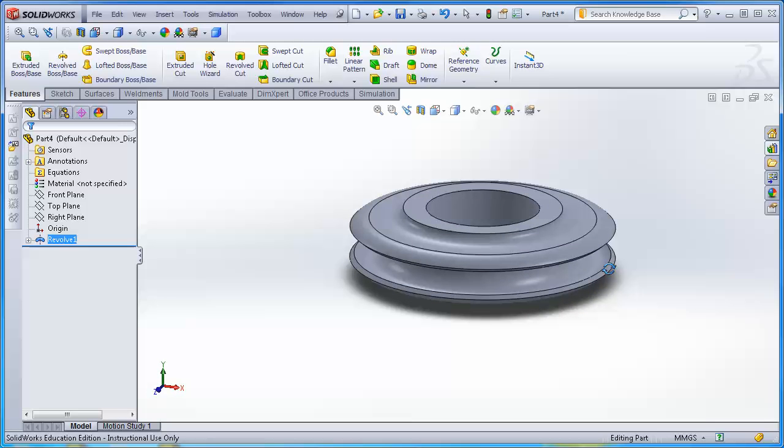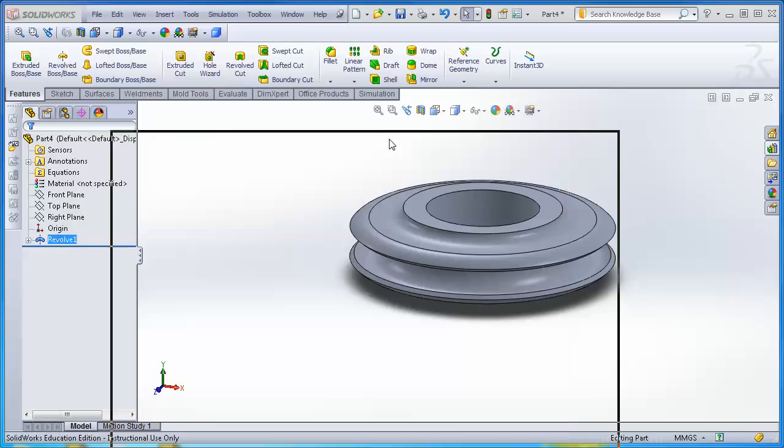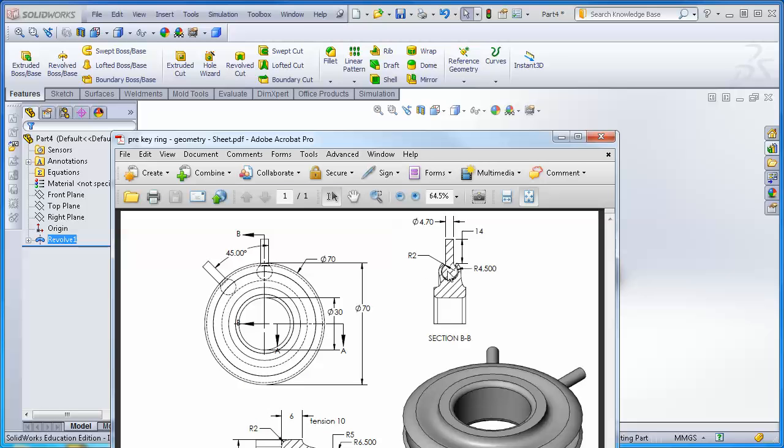And now I'm ready to go make the spherical cylindrical protrusions. This thing right here, notice it does have dimensions given, so I'm ready to make those. If I were to zoom in on this, I would see that there's a clearance around these parts, and so actually this is going to be one SolidWorks part, which is actually going to be multi-bodies. And so we're going to have to deal with that in just a minute, maybe for the first time.